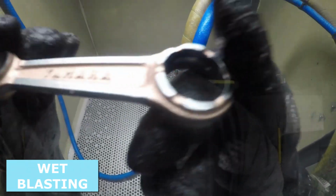Vapor blasting is also great surface preparation for bonding, polishing, welding, or coating of parts and components. Cleaning the topography of the surface, this provides an excellent surface for plating. The flushing action of combined water and abrasives allows optimum surface cleanness and preparation for final metal plating: nickel, chrome, brass or silver. Engine building with vapor blasting.